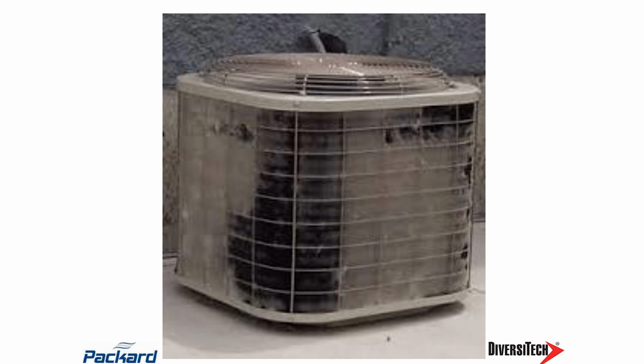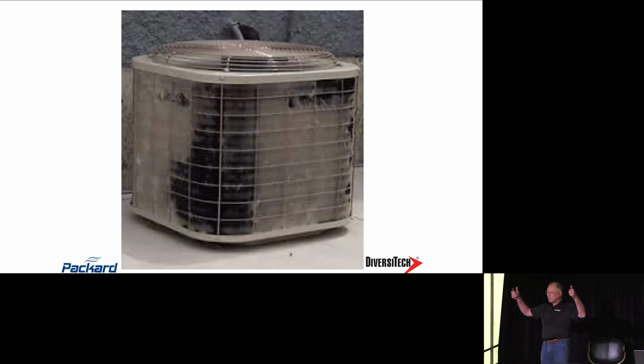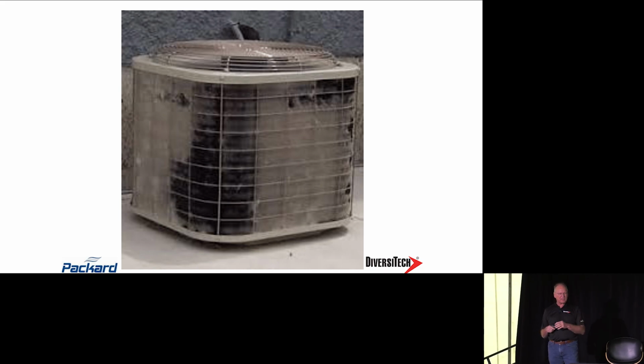So what's that going to do to the amps on the motor? Cause them to go up. What would that do to the operating temperature of the motor? It would increase it. What would that do to the speed of the motor? Slow it down a little bit. So when we think about load, it's going to impact the performance of that motor. And if I increase the load, the motor's probably going to slow down a little bit. If it slows down a little bit, I could probably see that I've increased the load just by looking at my amps on that. And my amps would go up.